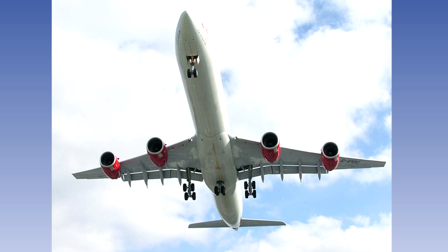The method usually employed to move the centre of gravity is by transferring fuel between tanks located at the nose and/or tail of the aircraft. The Airbus A340, for instance, has a fuel tank in the tail specifically for this purpose. Fuel is automatically transferred between this and the wing tanks to maintain the C of G as close to the centre of pressure as possible.